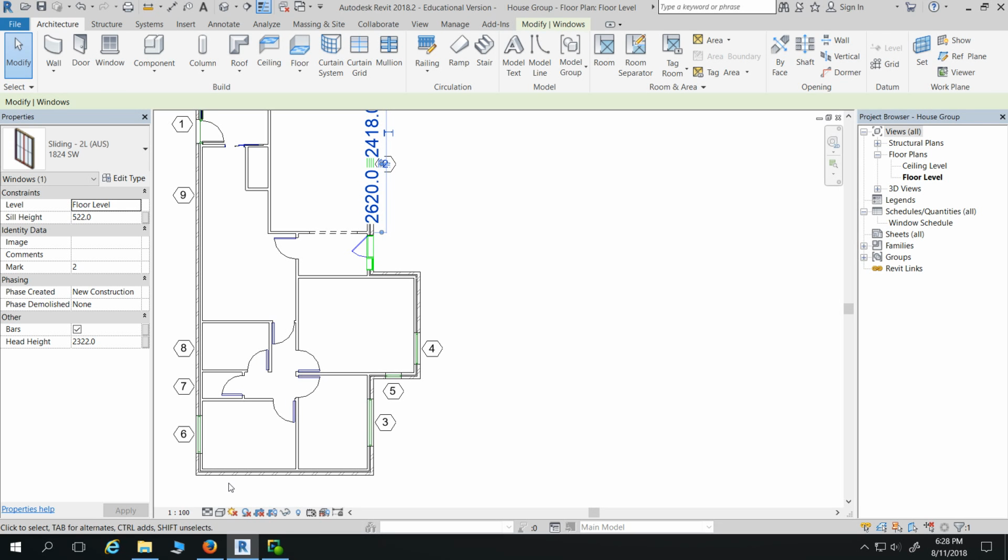This will be down the bottom, so that's better. Oh yeah, so we're going to slide. Sliding to go. For this instance, you can just choose any size window from the sliding category, because it doesn't really matter. We're going to duplicate and make our own, because they say they're Australian standard sizes, but they're not. If anyone's worked in brick dimensions much before, I don't care much for brick dimensions. I hate bricks. But unfortunately, I work for a builder that builds primarily brick veneers, so I'm stuck.